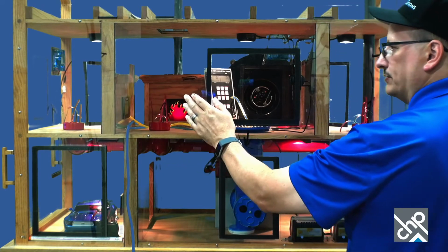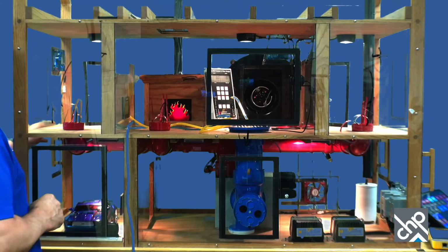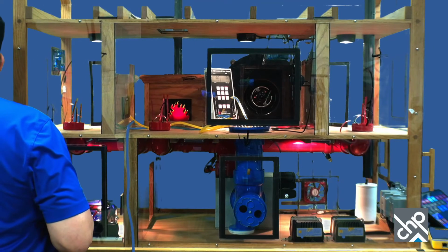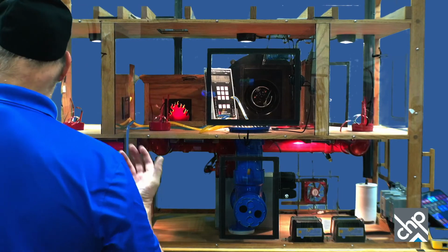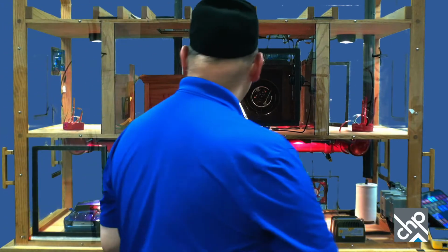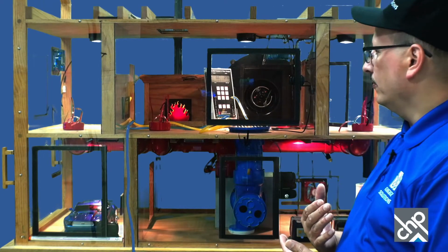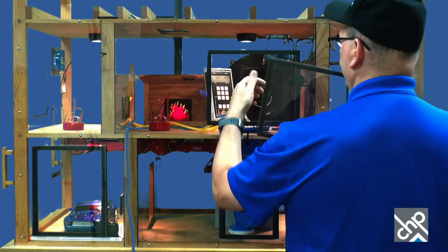So now I'm going to close this door, and we'll watch those pressures again. I'm going to keep it on this view. Close this door. You can see my hose going into the door. I'm going to close the door here. The door is now closed, and now it's coming back down again. So what we want is the smoke to go out the chimney when the door is closed. So what you want to do is equalize that pressure. So you would open that up until the pressure drops. In this case, we're at 27 there, and I would open up the door until the manometer pressure drops.